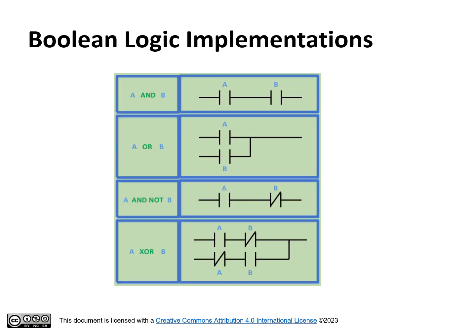A combination of these relay logic instructions in ladder logic can be used to implement a Boolean expression. A collection of basic Boolean expressions that are implemented in ladder logic instructions is depicted in the figure below. Notice that the serial construct implies an AND Boolean operator, and a parallel construct implies an OR Boolean operator.